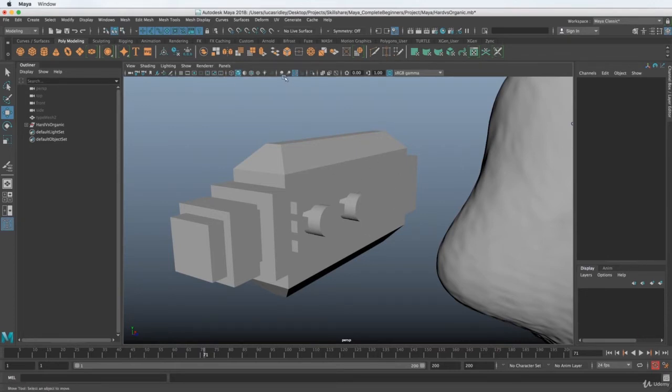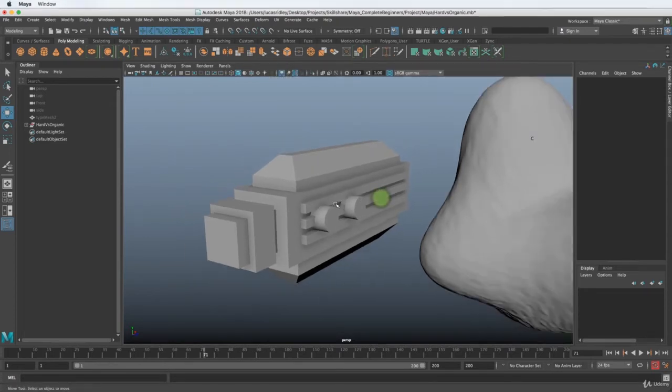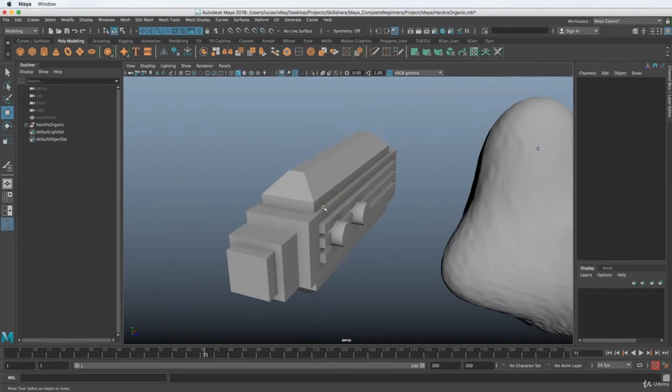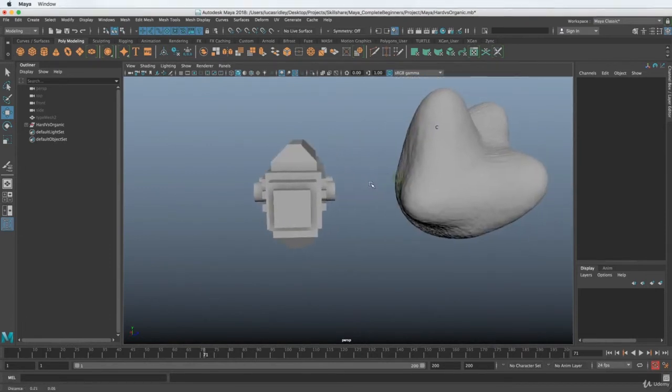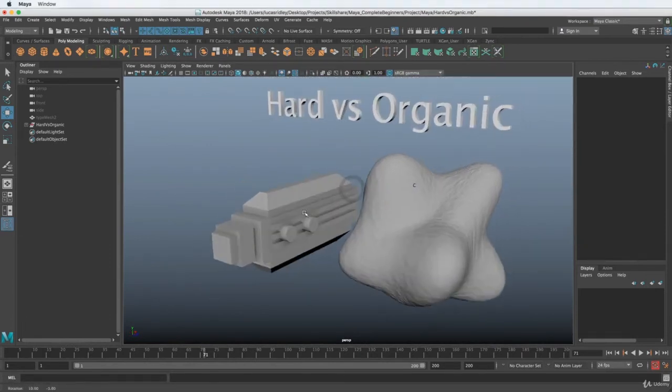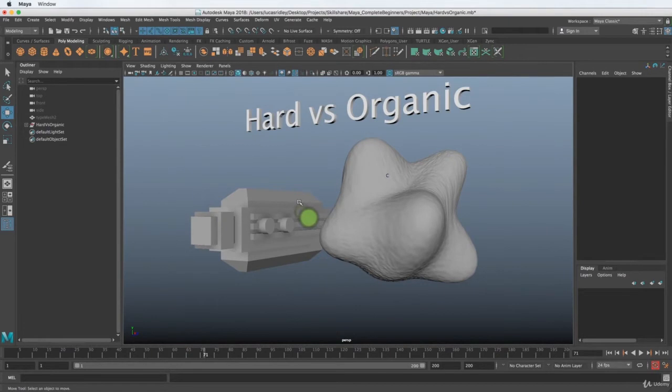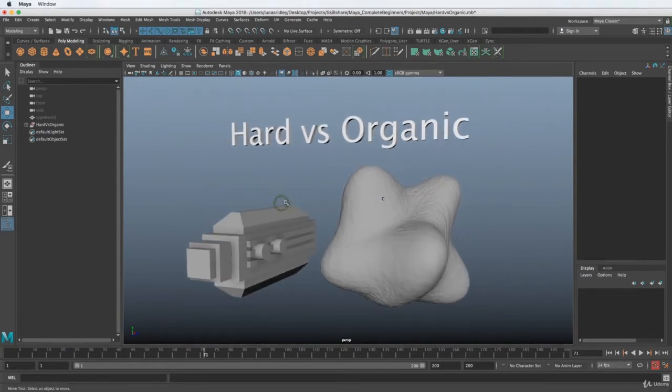If we turn on ambient occlusion, which is this little button up here just next to the anti-aliasing, we get ambient occlusion, which basically shows us areas of geometry that are close together and darkens those corners and inset areas. So now we can see that model a little bit better now that we have those two viewport options turned on.